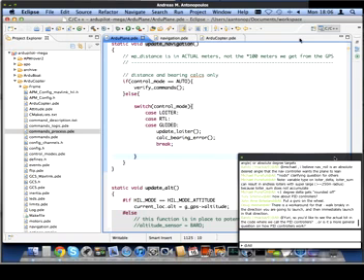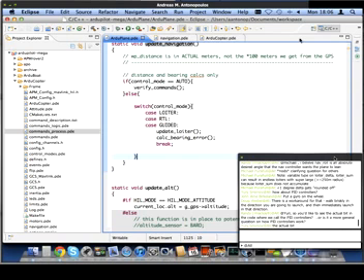For landing, again, you have a land operation in the mission, and that land specifies the target location where you want to touch down. The plane tries to glide in along a smooth glide path to touch down. It's highly recommended that if you are going to do automatic landing, you have an airspeed sensor. The reason for that is landings are typically performed fairly close to the stall speed. You generally don't land at high speed. If you're close to the stall speed, it's quite critical that you not go below it, otherwise your aircraft will stall and just fall out of the sky.